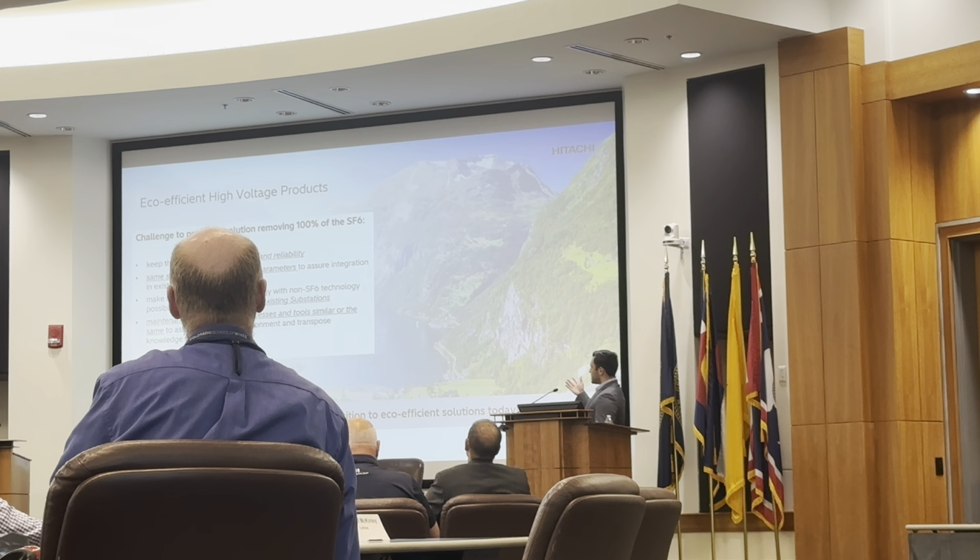We can also fit the same GIS in the same footprint of the same substation. So if we have an extension, if a GIS building is being extended, and it's already SF6, it could be SF6 free because it's going to easily connect with the other one. And of course, you have that pressure differential in between, but you can easily connect both technologies together.